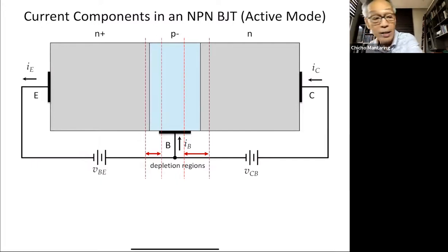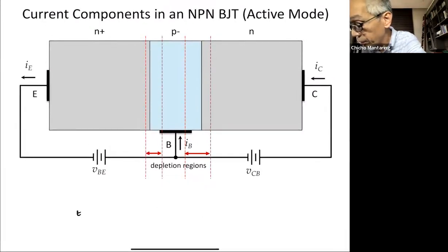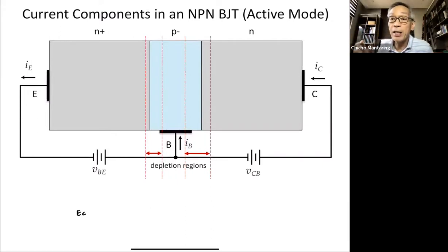So I'm going to show again here just piece of C. If I take a look at piece of C, because of the forward bias, my built-in potential is going to become smaller. Remember that in a forward bias PN junction, the bending becomes smaller, and that is what allows diffusion. When it's open circuited, you have drift and diffusion canceling each other out, but when it becomes smaller, then you have now more diffusion than drift. I explained this in the last meeting.